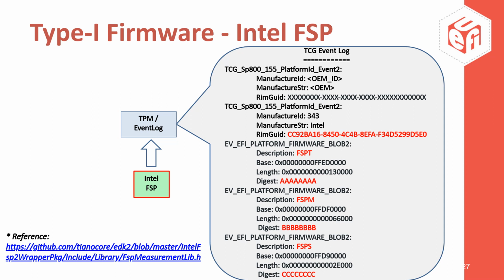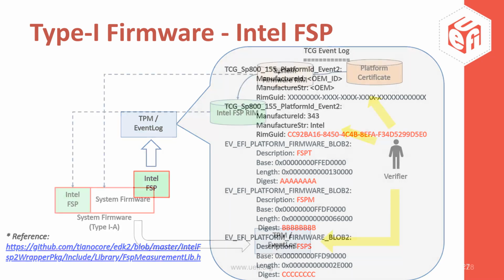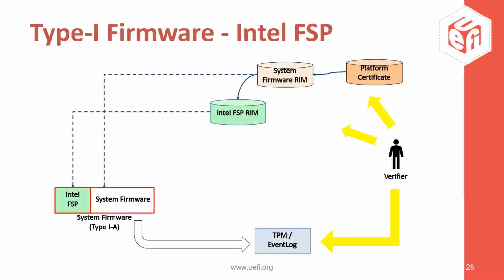And so these are actually sampled directly from the SPI NOR flash for that running system. So the former slide was offline creation of the expected measurements, put them in the RIM. This slide is an actual system booting, generating a TCG event log in host memory. And then this slide is kind of the fusion of the two.